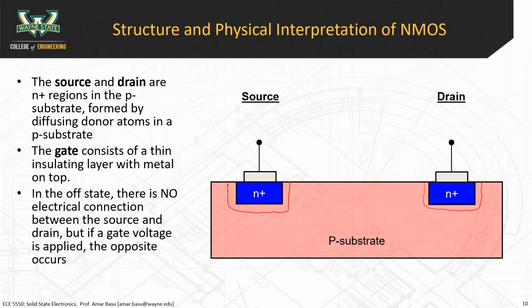Okay. Now, the next part of the NMOS device is the gate. So the gate goes right in the middle. All right, so from the last diagram, we're going to try to create a channel between the source and the drain. All right, this is P-type, and we want to switch that material from P-type to N-type and form a conductive channel between the source and the drain.